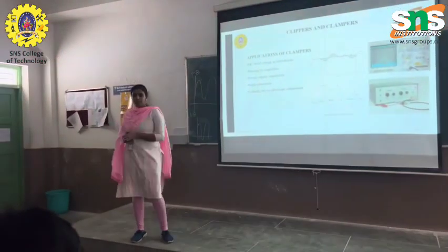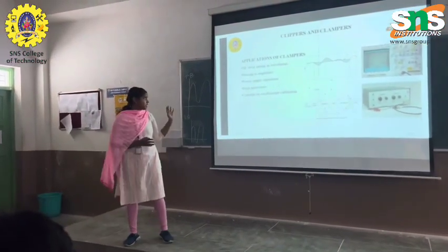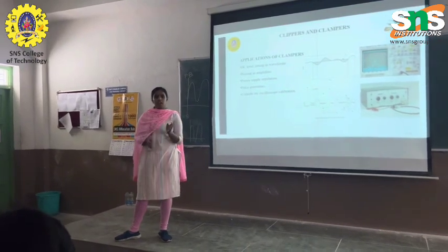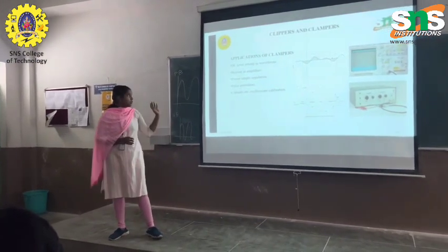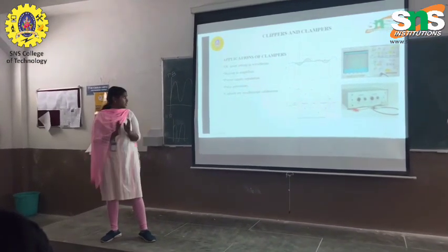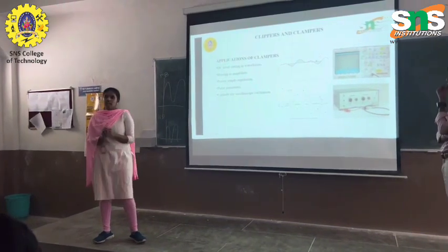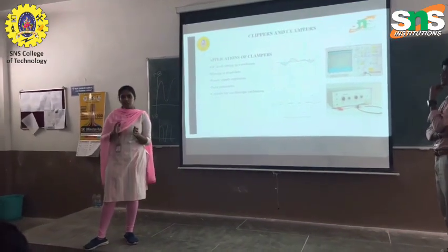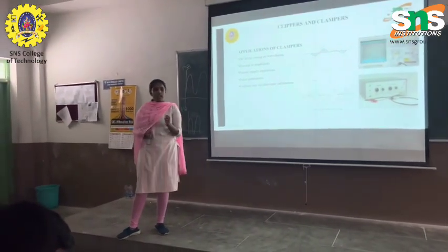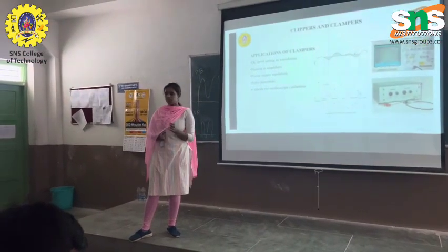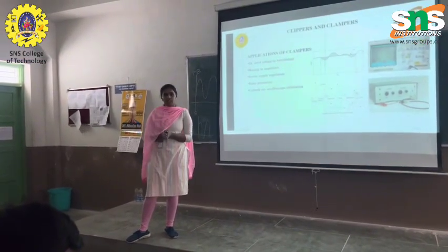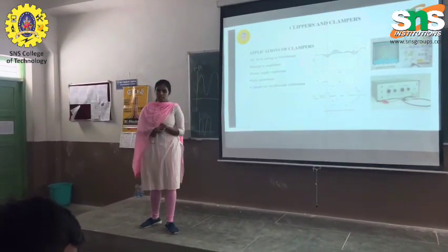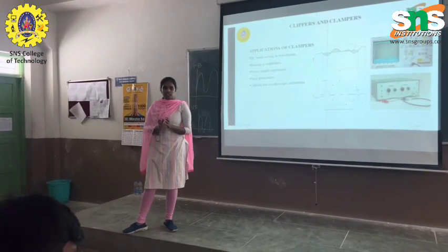And there are applications for clampers too. First is to set the DC level in the waveform, for biasing amplifiers and power supply regulation, in TV receivers to maintain pixel processing, in medical instruments to ensure readability, and for radar and communication systems in signal grounds.